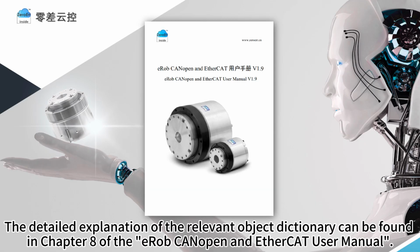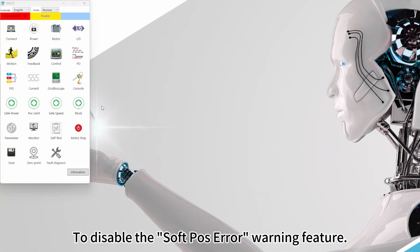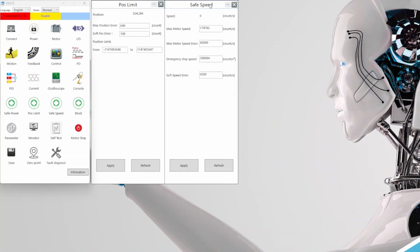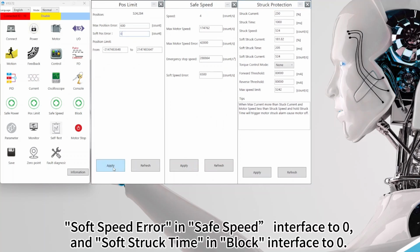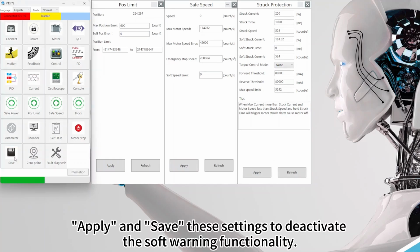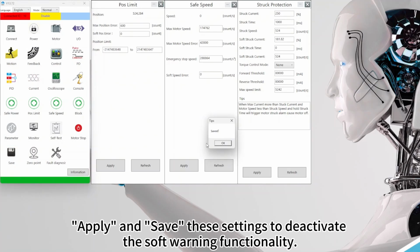The detailed explanation of the relevant object dictionary can be found in Chapter 8 of the eRob CANopen and EtherCAT user manual. To disable the soft position error warning feature, set the soft position error in position limit interface to 0, soft speed error in safe speed interface to 0, and soft stuck time in block interface to 0. Apply and save these settings to deactivate the soft warning functionality.